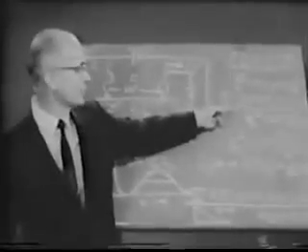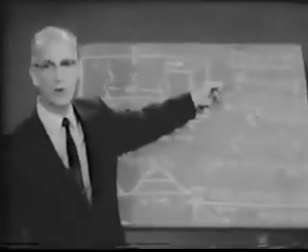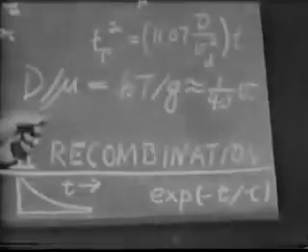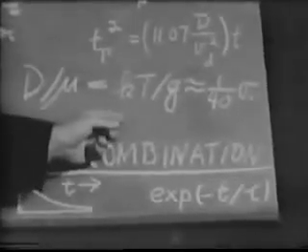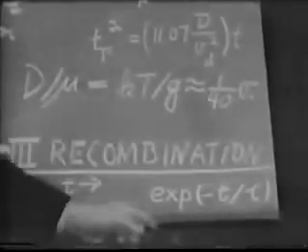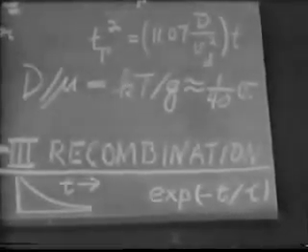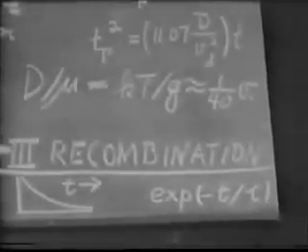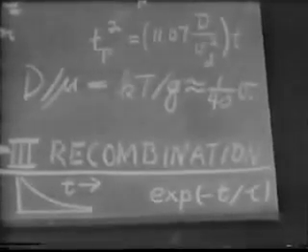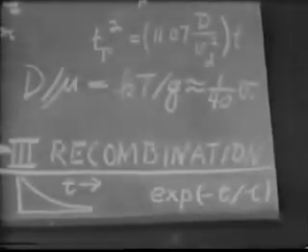The diffusion constant and the mobility of the holes have values governed by random thermal motion. The importance of thermal motion is expressed by the Einstein relation, which requires that the ratio d over mu be equal to kT over Q, in which kT is random thermal energy and Q the electron charge. This ratio has the dimensions of volts and is called thermal voltage.